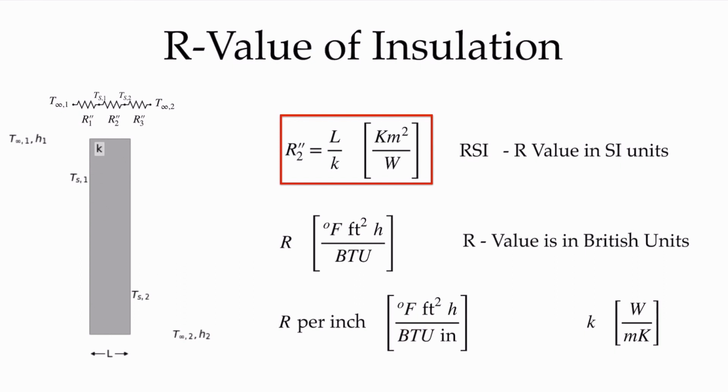And if we look at this being an area divided by a length, that will give us units of length, and it's on the top. So that's equivalent dimensionally to the meters in there. And of course, the degrees Fahrenheit is equivalent to the degrees kelvin. So the R value per inch is actually the inverse of the thermal conductivity expressed in extremely bizarre units.